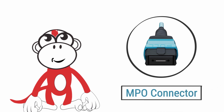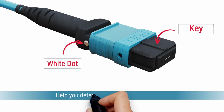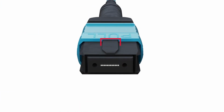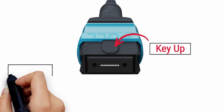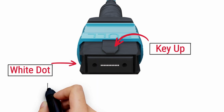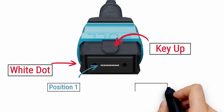MPO connector. Each connector features a key and a white dot to help you determine the orientation of the fibers. When the key is located on top of the connector, this is known as the key up position. In this position, the white dot is located on the left side of the connector to designate where position 1 is located when the connector is plugged in.